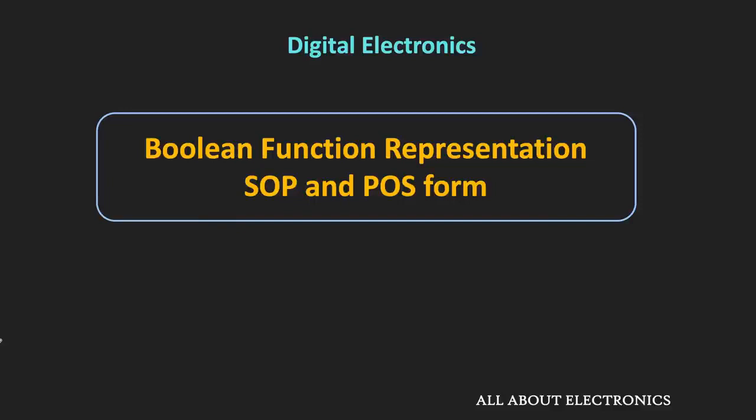So in this video, we will see how to represent any Boolean function or Boolean expression in a sum of product and the product of sum form. And we will also understand the concept of Minterms and Maxterms.